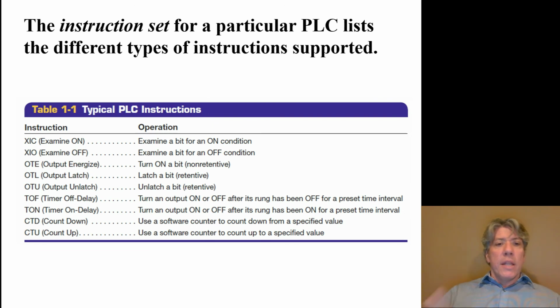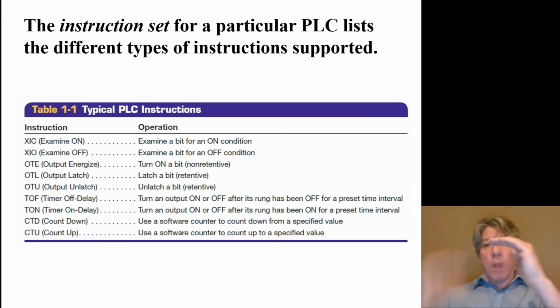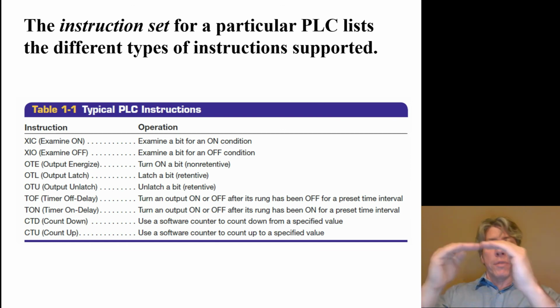For example, the XIC and XIO instructions basically allow power to pass when what they're sensing is high or low. Very often, it's very beneficial to have something come on when there's a change from high to low, a transition: a so-called rising edge when it goes from low to high, or a so-called falling edge where the signal goes from high to low.